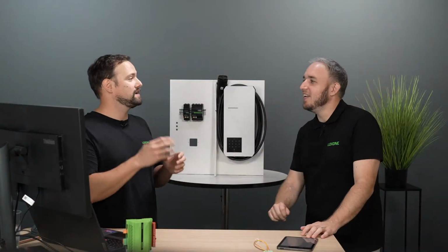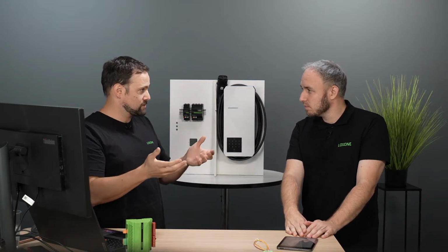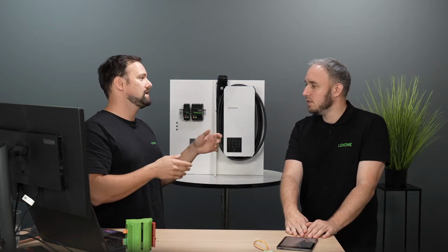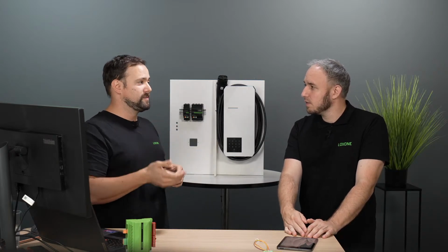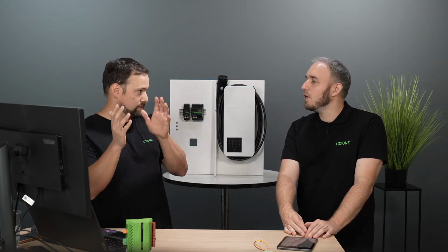Say you have an electric vehicle and you get a charging card, maybe from Shell Recharge or any other vendor out there. You can now go to your Wallbox and hold this RFID charging card to the NFC Code Touch, and it will read it and transfer it to the OCPP server of the charge point network, which then decides, yes, that person is allowed to charge, and it will start charging. You will be billed automatically because the Miniserver then reports the charging session to that backend.